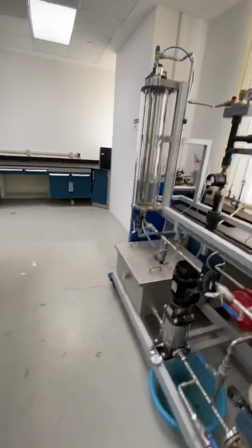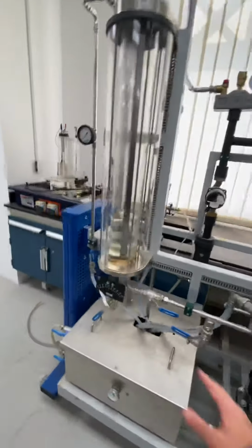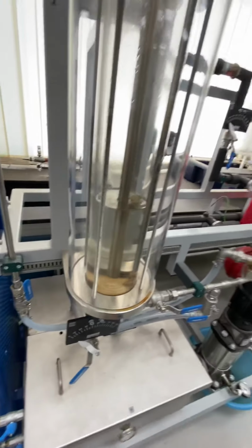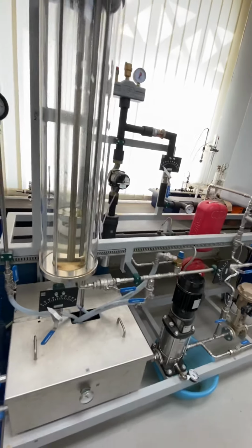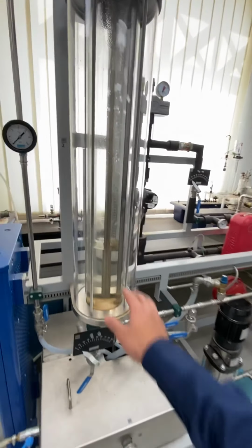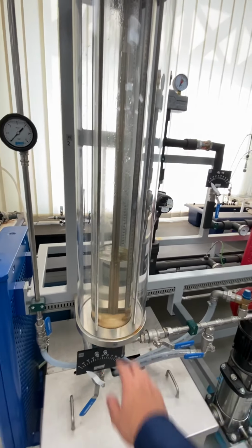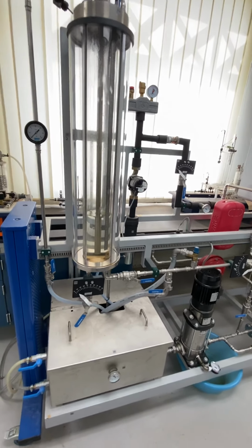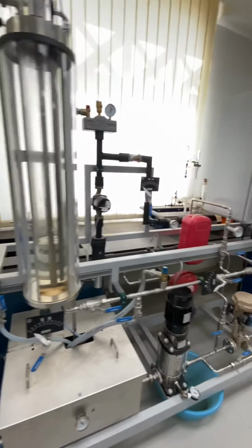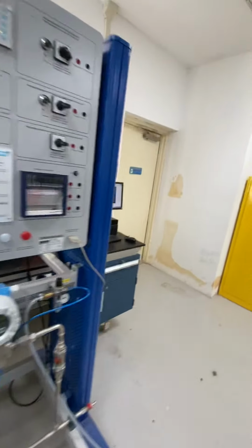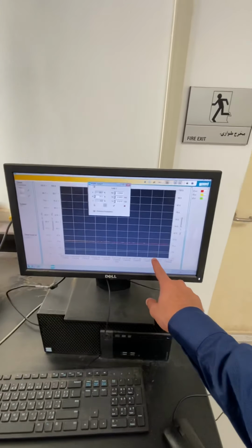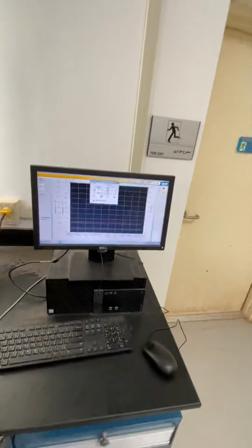Now once I open valve number 14 fully, what we are going to see is that the level will drop, because as we said, the more you open this valve, the more flow out of the tank, and that brings the liquid level below the set point. So a lower level means that we have a negative error in this situation, and with the negative error for the inverse action, we will see that the controller output signal, which is the green one, will start to increase.